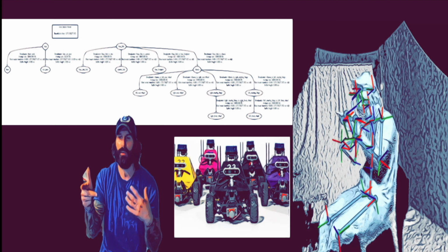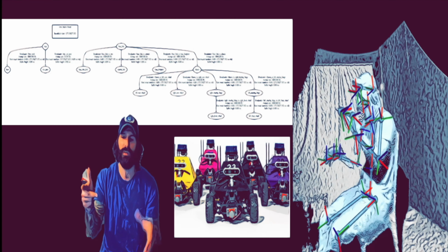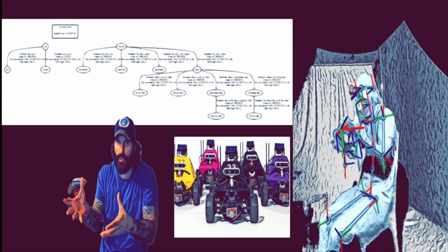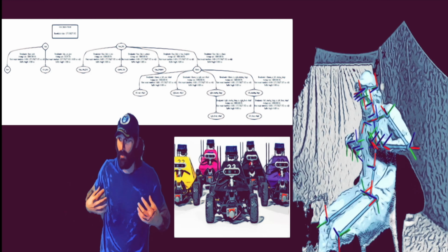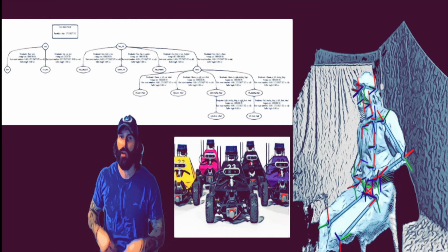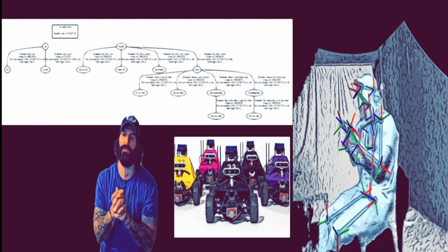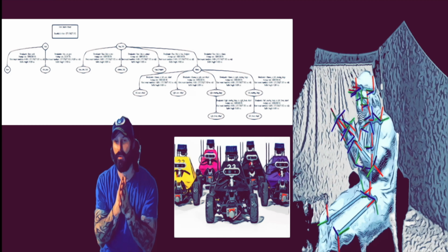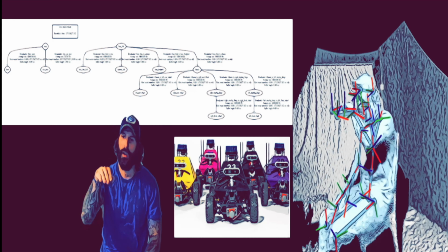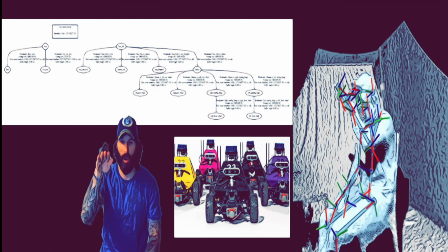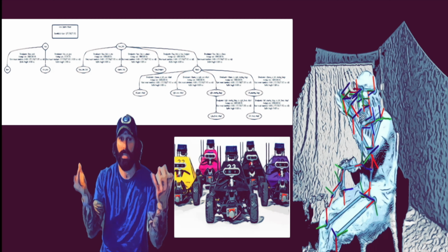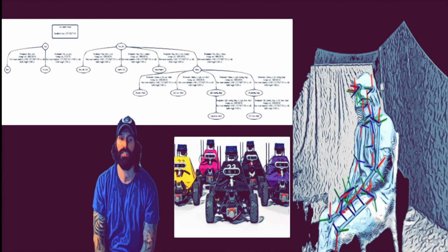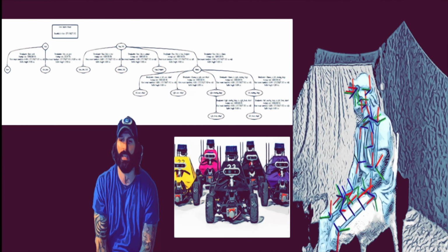For us, Euler angles are more understandable, and it's a good reference for decomposing rotations into individual degrees of freedom, like for kinematic joints on robots, just like you see here on my body with a base link and a bunch of individual links. But they had significant disadvantages when it comes to computation in computers, mostly on ambiguity, and we call it the gimbal lock. As the pitch approaches 90 degrees theta around, you'll end up seeing that it'll fail. And quaternions essentially is a 4-element vector which can be used to encode any rotation in the 3D coordinate space, and it has those advantages.